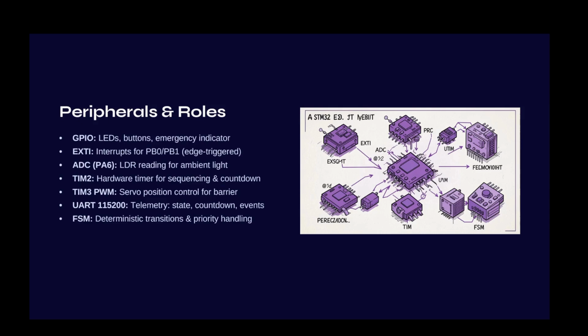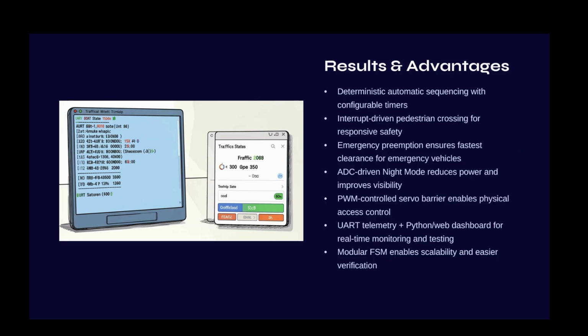Finite state machine. The most interesting concept I learned was the finite state machine. Each operating mode, normal, pedestrian, emergency, and night, is treated as a separate state. The controller moves between these states depending on timers, interrupts, and sensor values. Using FSM made our program organized, easier to debug, and very reliable. This internship gave me practical experience in embedded C programming, STM32 HAL libraries, debugging, and real-time embedded system development.